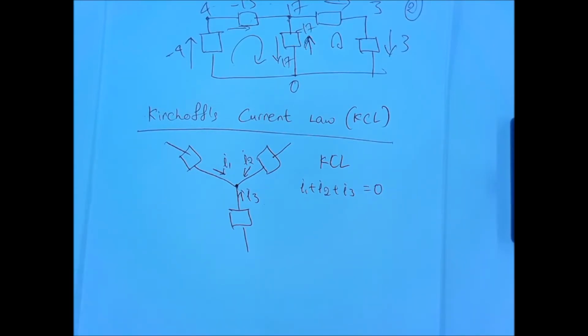In reality, that's not necessarily true. KVL should always hold for electric fields and for electric potentials, right? But KCL need not hold when there is charge being accumulated. But we are assuming charge will not accumulate. And hence KCL. So for all our circuits, we'll use three things: Ohm's law, KVL, and KCL, and that's pretty much it to solve resistive circuits. Right? Okay. Any questions so far?